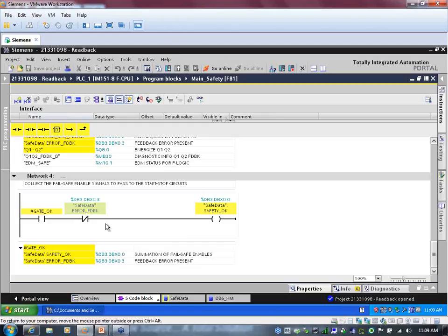And here you just saw that what I did, remember I had that contact in the start command rung in OB1, is I've just collected the status of my 2 blocks here and summarized it, so I only had to bring one contact out to the standard module. So let's look at, let me go back to, let's see here.